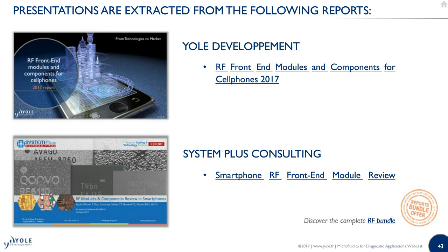Now, if we talk again about 5G millimeter wave, as of today the limiting technology seems to be filtering, of course, when we move to these very high frequencies. We haven't seen any working solution that can withstand the low cost and the high integration needed for smartphone integration. Only one player claims to have a solution, Qualcomm, and that's what I think Stefan tried to explain.